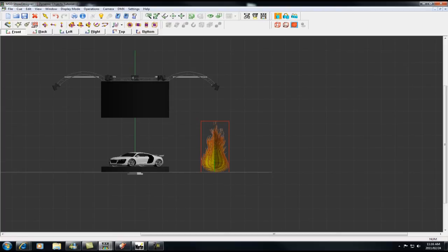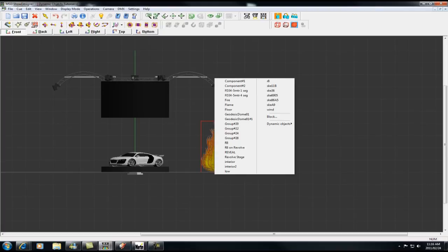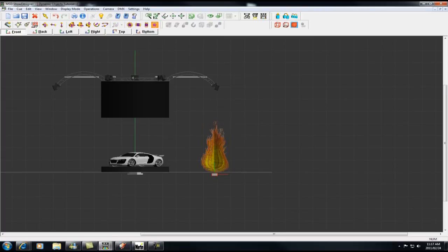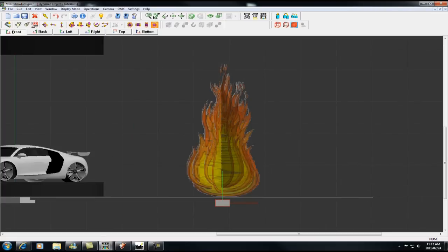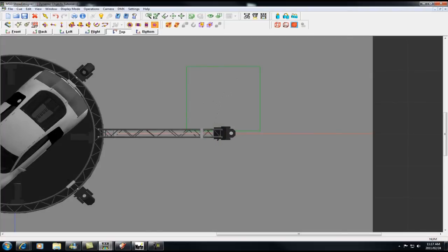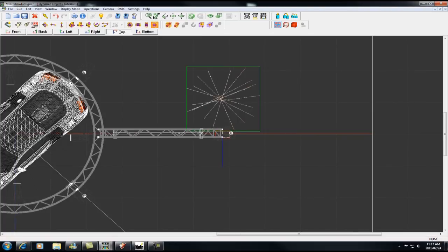You then insert your scalar, come to Dynamic Objects, choose Scalar. I'm going to choose a large one for now, just to make the illustration easier. It then puts a little block underneath. You want to ensure that your alignment is correct. You can do that by going to Movement and moving your object directly underneath your actual 3D object or shape that you want it to scale.